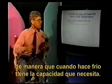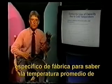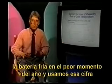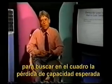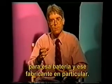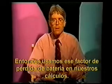the capacity we need. So we would refer to some sort of chart like this or a specific chart from a manufacturer and read the expected average cold battery temperature in the worst part of the year and use that figure to read on the chart the expected loss of capacity for that battery, for that particular manufacturer. We would then use that battery loss factor in our calculations.